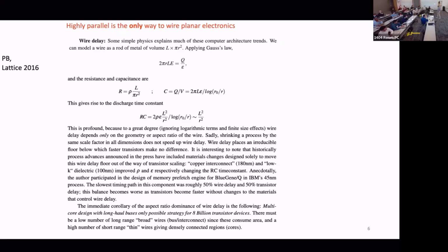And similarly, there's this thing called high bandwidth memory, where they can stack chips. It's like the medieval Europeans were really nasty to each other and had these things called Iron Maidens, where they would put spikes through people, right? They've got spikes rising through a tower of chips. And the whole point of that is you then have a nice aspect ratio for the transmission. You can clock the data in and out of the chip stacks efficiently, right? So, high bit rates. And that gives rise to current modern GPUs with high bandwidth memory, et cetera.